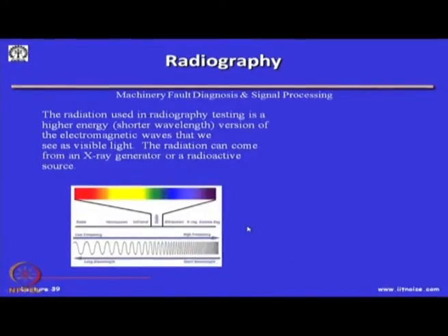So, what is this radiography? The radiation used in radiography testing is a high energy, shorter wavelength version of the electromagnetic waves that we see as visible light. The radiation can come from an X-ray generator or a radioactive source.